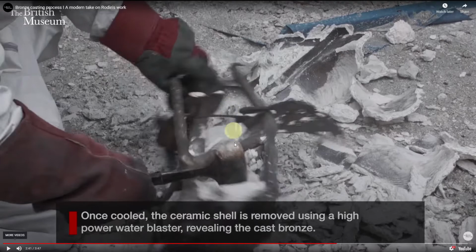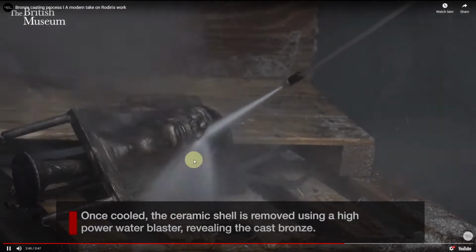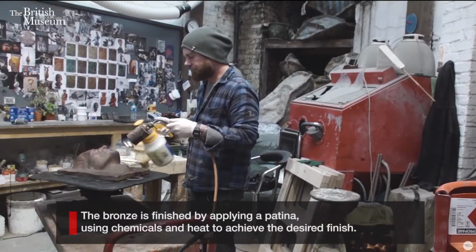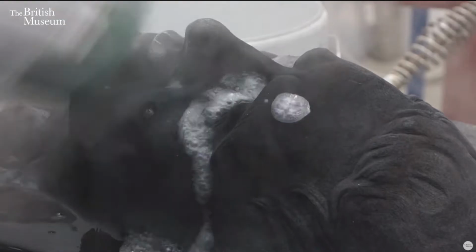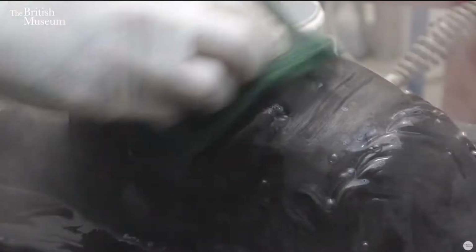What's cool, you have all this work and then this rod system and everything. So you have to break the mold, give it a power wash to clean it out, and then use the heavy tool to clean it up. Patina is applied from time to time, but I prefer just the raw color of the bronze. Patina is pretty much giving a chemical bath to a bronze surface to create a certain effect.